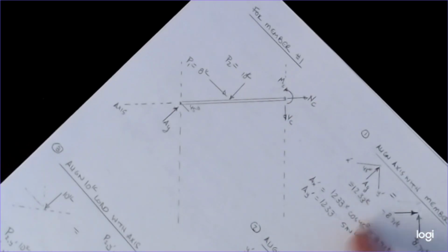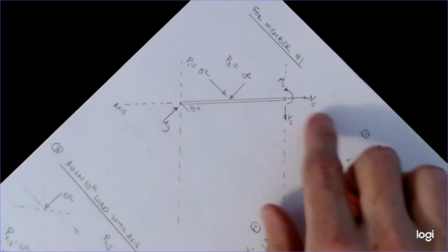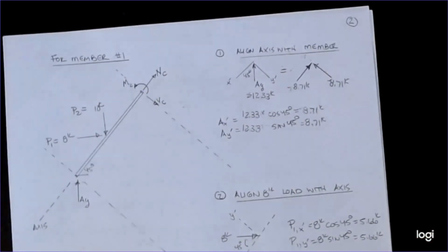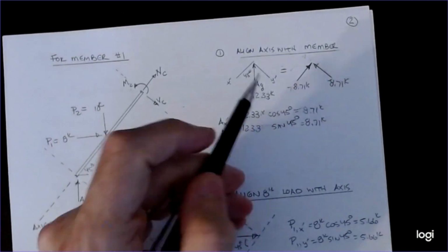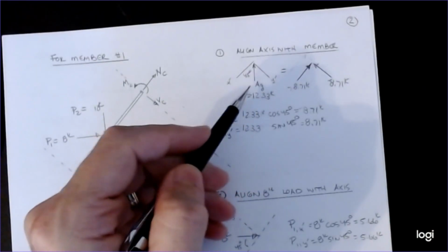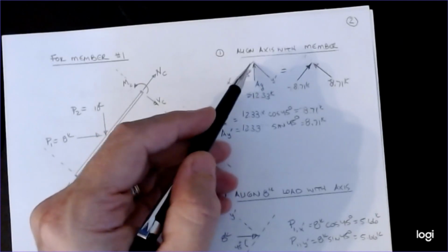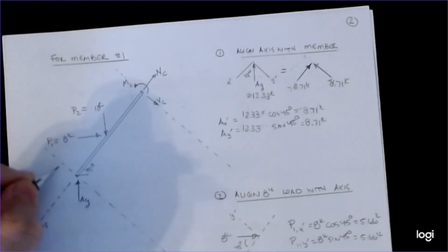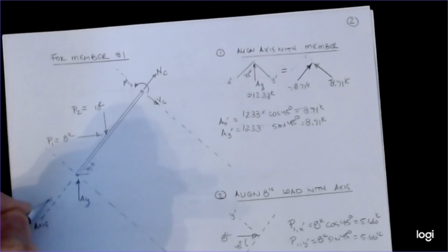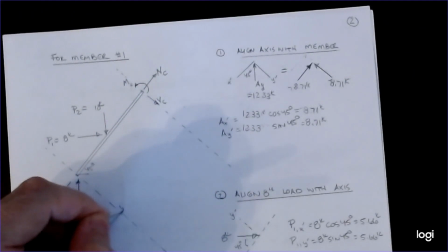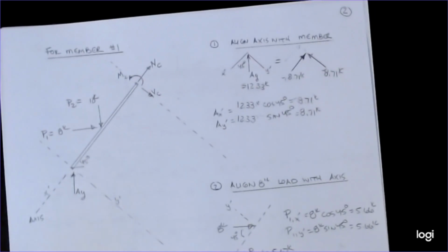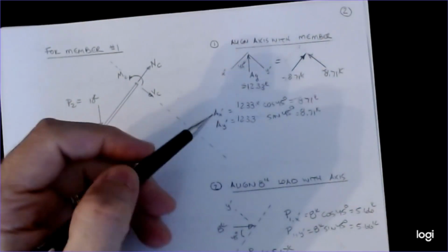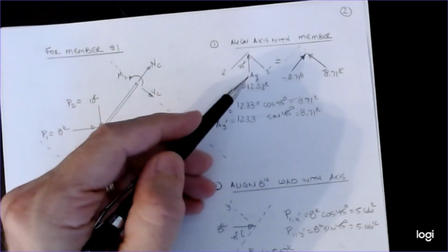So we've got to come in and get these guys converted over so I can now work with shear and moment. All right, so we'll turn our paper back around and look at this. Let's start with the reaction at AY. So if I do AY, to get myself onto that aligned system, what I'm calling X prime and Y prime, to get my axes lined up. My X prime is this direction and my Y prime is on that one. That kind of gets us our orientation. And so I can break this into components.